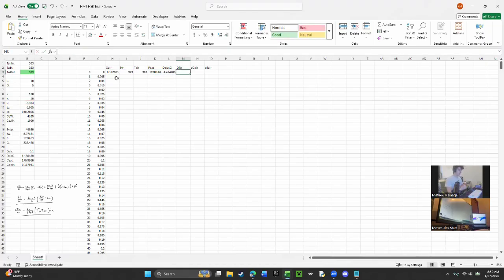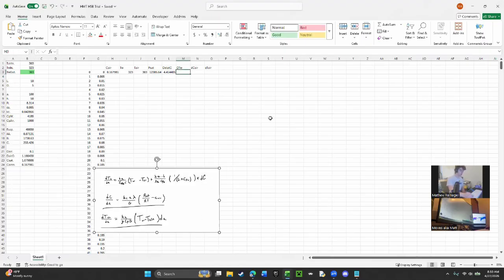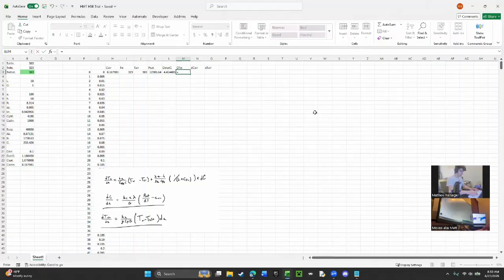Okay. So this is going to be the very long equation, the reason why I simplified this equation just a little bit. So to find the change of the temperature of the water, we're going to plug in the equation that we had solved for. So this is going to be the heat transfer coefficient multiplied by the packing coefficient, divided by the heat capacity of the air, multiplied by our liquid flow rate.